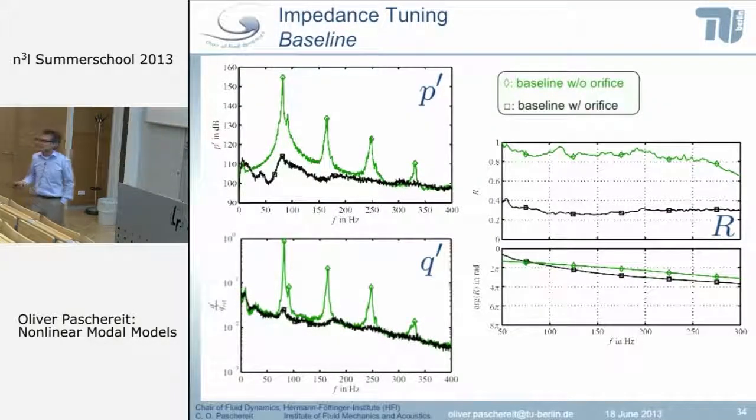It's not completely one because we have all kinds of stuff mounted at the exit of our combustor, so it's not a measurement error. If we dismantle the test rig and take away all the loudspeakers and all perforations we have at the end of our combustor, this is actually one and behaves very nicely like theory from Levine and Schwinger or others showing you this reflection coefficient.